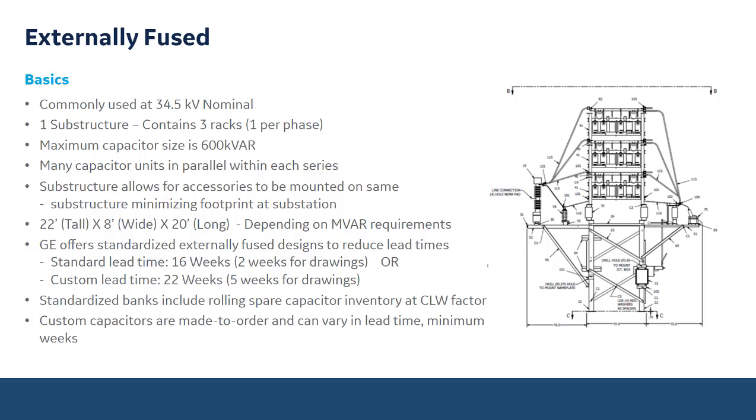We provide a catalog which will identify MVAR requirements at 34.5 kV, and there's a selection table, so you can select the MVAR requirements, which will include the cap switcher, the arresters, ground switch, and a PT. This is pretty much a standard offering, and we've had pretty good success with this.